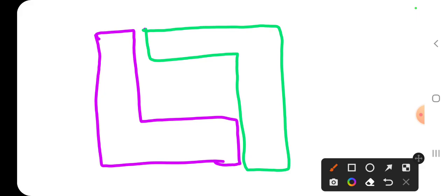By using two L-shaped laminations, you can construct the core in this fashion. So here, how many joints do you require? 1, 2. That means you can reduce the joints. In the previous case you need 4 joints, but here you need only 2 joints.